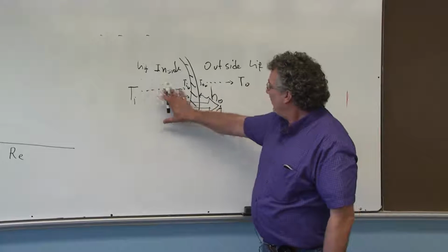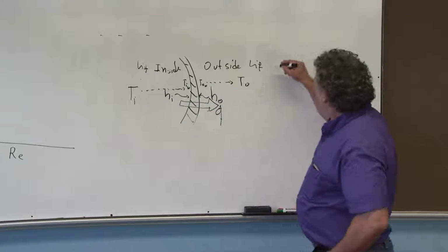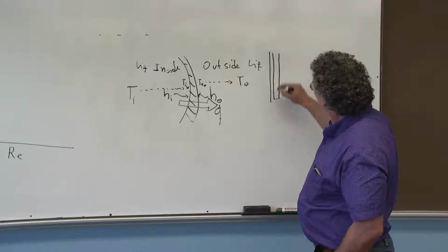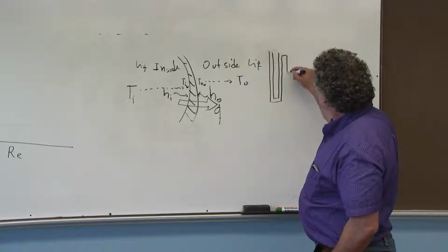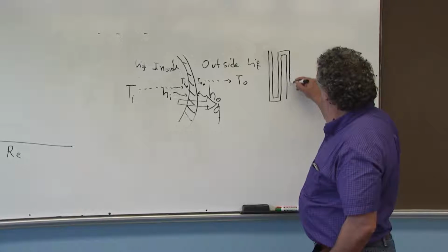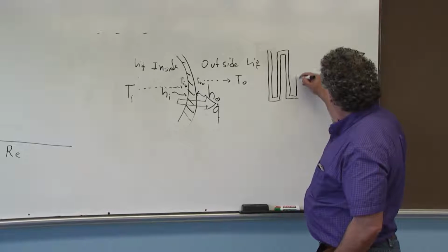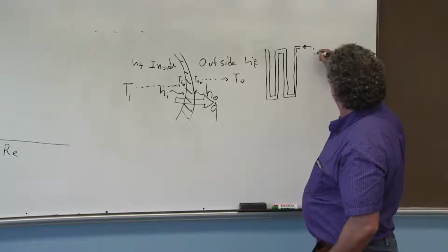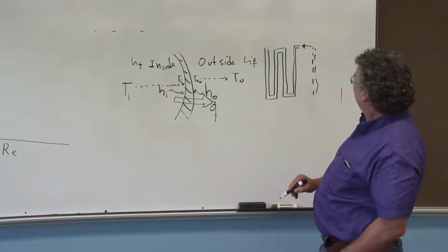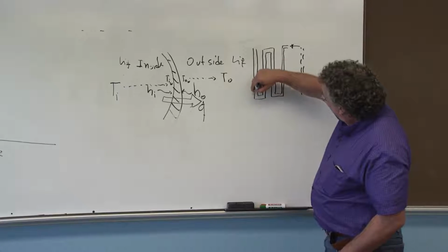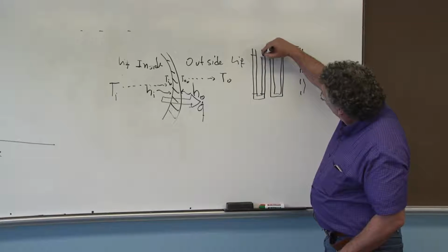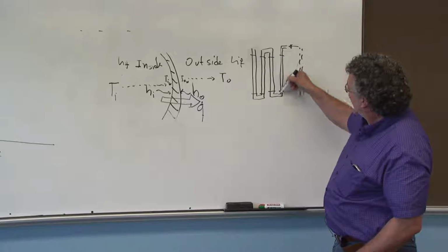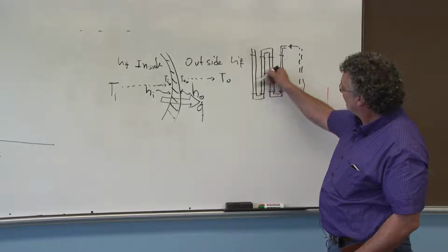So this happens at any specific point of the pipes. A moment ago you saw a drawing where we had these four pipes represented as a kind of labyrinth. Here the fluid is coming in hot from the preheater with the steam, and each one of these sections is being cooled separately, which means the temperature of the circulating fluid decreases as it travels.